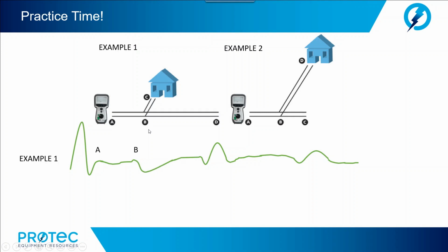Now, at this point, the TDR pulse is going to split. Part of the TDR pulse is going to continue traveling along the main feed, while part of the pulse breaks loose and travels along the branch circuit. The events that we see next are going to be based on time of flight. For example, in example 1, we see the reflection from point C, the client, because the branch is shorter in physical length than the main feed going to the end termination.